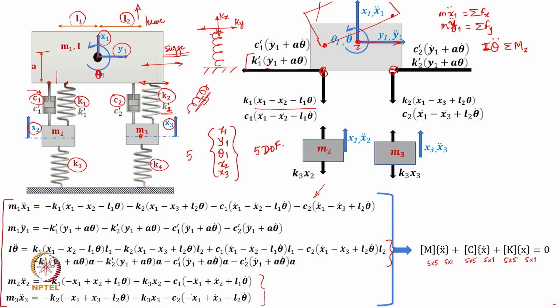That is going to give you a force balance in a multi degree of freedom system, mx double dot plus cx dot plus kx equal to 0. For most of our vibratory systems in the mechanical engineering domain, by and large all the matrices are going to be symmetric matrices, and they are constant. So, they are not going to depend on time, and the only independent variable here will be time, and then x double dot and x dot, these are all the responses of this multi degree of freedom system.